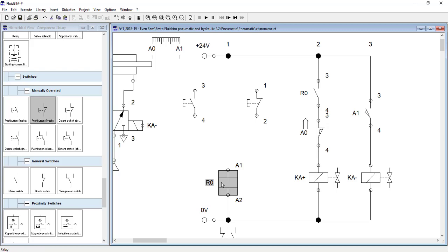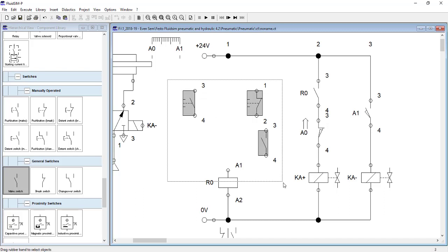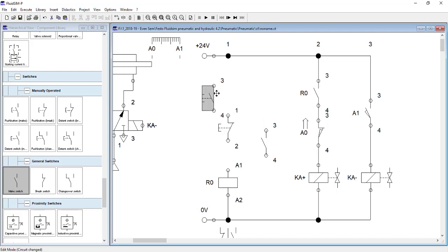And this is a relay coil which I have. Plus, I will need a relay NO switch. So these four things are required to create a latching circuit. So how is a latching circuit? First of all, there is the NO switch, the start switch. Then there is this NC switch. The NC switch is connected to relay 0.